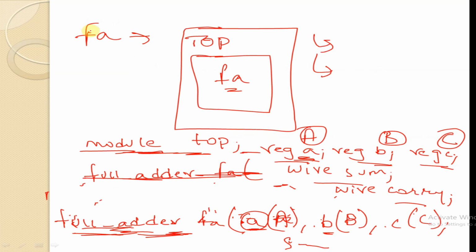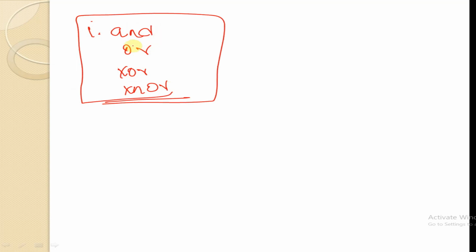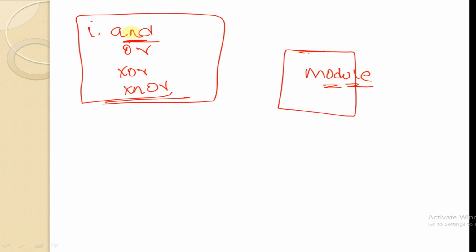Likewise, the developers, the ones who invented the language, have written primitives. They have written the logic for these primitives: and, or, XOR, XNOR. When we are writing our design and using these primitives, we are just instantiating them inside our module. Let's see an example here.